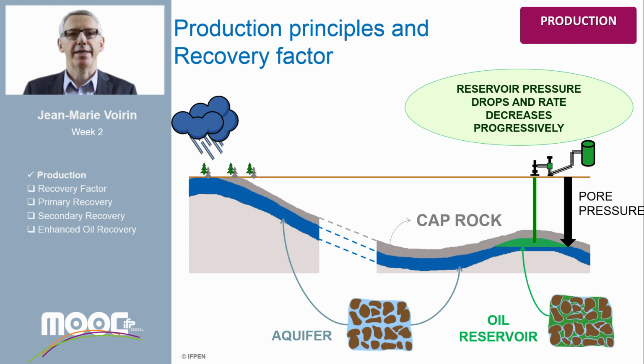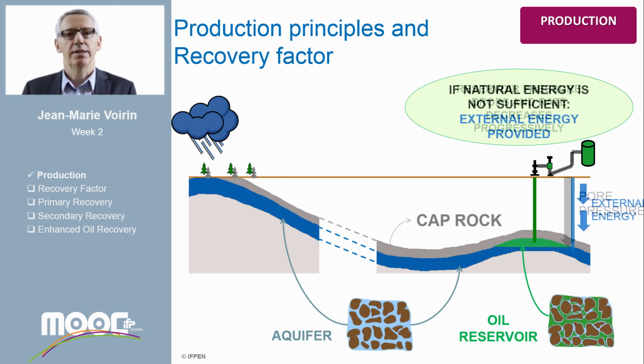The well production rate is a function of the pressure drawdown, which is the difference between the pressure at the bottom of the well and the reservoir pressure further from the well. It is also a function of the fluid ability to move through the reservoir to the well. As oil is removed, the reservoir pressure will start to drop, and progressively the rate will decrease due to the change in drawdown. The oil quantity that can be produced from a reservoir is called recovery.